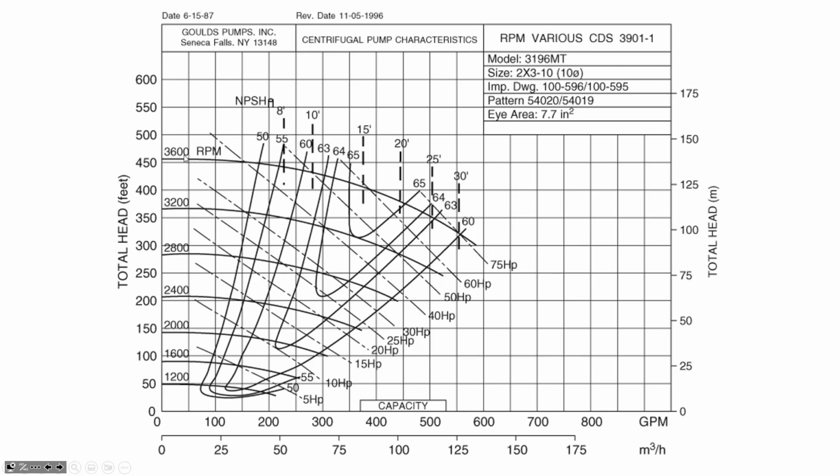Now notice the curvature of this figure, which is similar to that video we watched, where it showed the pipe which was at first horizontal and there was a really high flow rate because there wasn't any head that the pump was working against. But as you inclined the pipe and the pump had to work against some load and create additional pressure, the flow rate decreases.